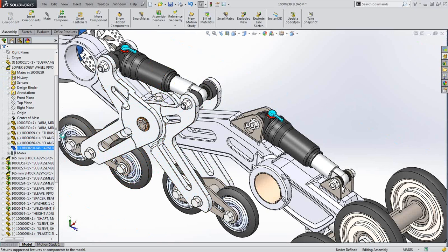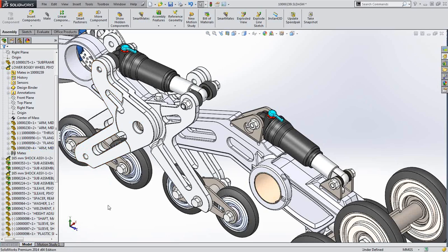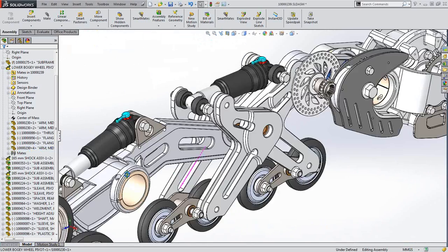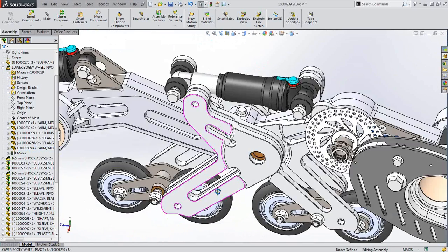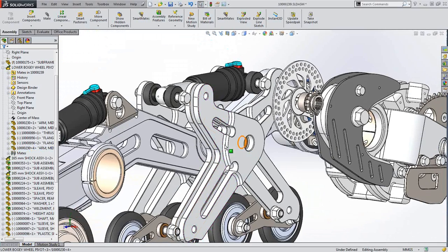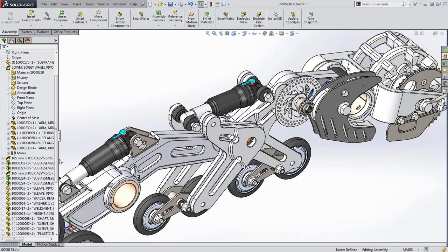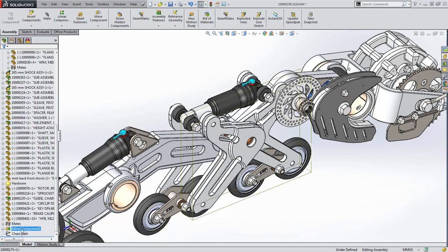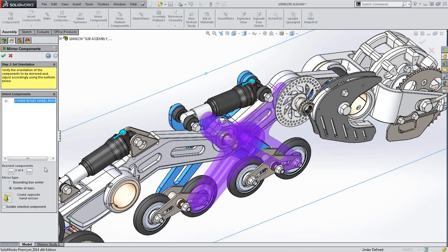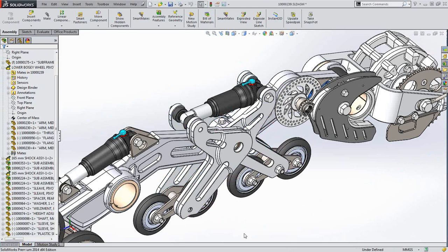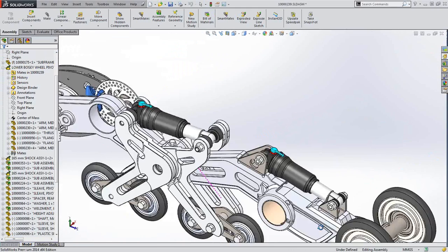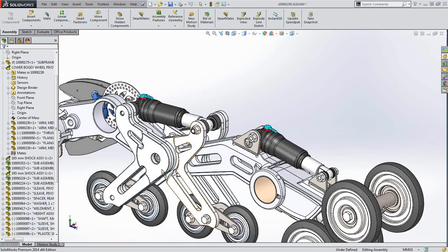But if I unsuppress this part, that is throwing off the center of mass, so now you'll notice that this doesn't line up correctly with the axis here, or the bolts up here. So if that would have instead been mirrored about the centroid, the center of the bounding box, you'll see then it would maintain the correct orientation and position.